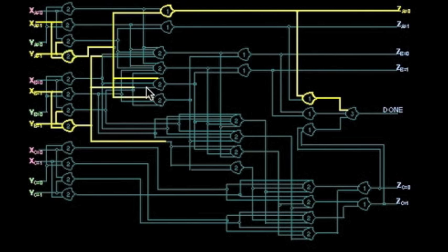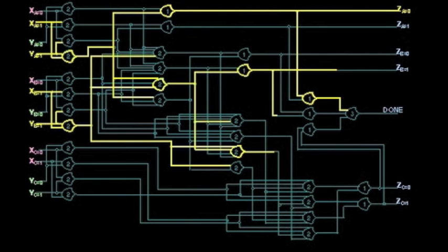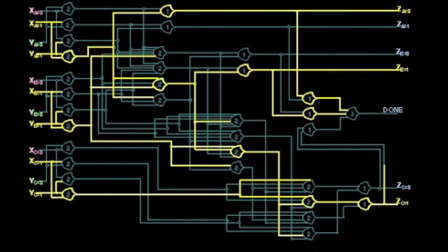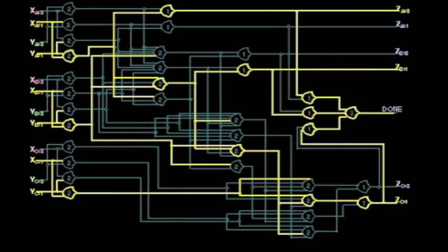Now this indifference to time reflects back to the input in that it doesn't matter when the inputs arrive or in what order the inputs arrive. When an input arrives, it will begin propagating through the circuit, presenting to gates and trying to meet thresholds. Okay, so let's continue on with data propagation. It goes through the circuit. So now we have all the inputs that propagated through all the outputs. Now the outputs have all transitioned to data. And so the input data wavefronts have flown all the way through the circuit to the output, and we have a logical signal confidently telling us that we're done.